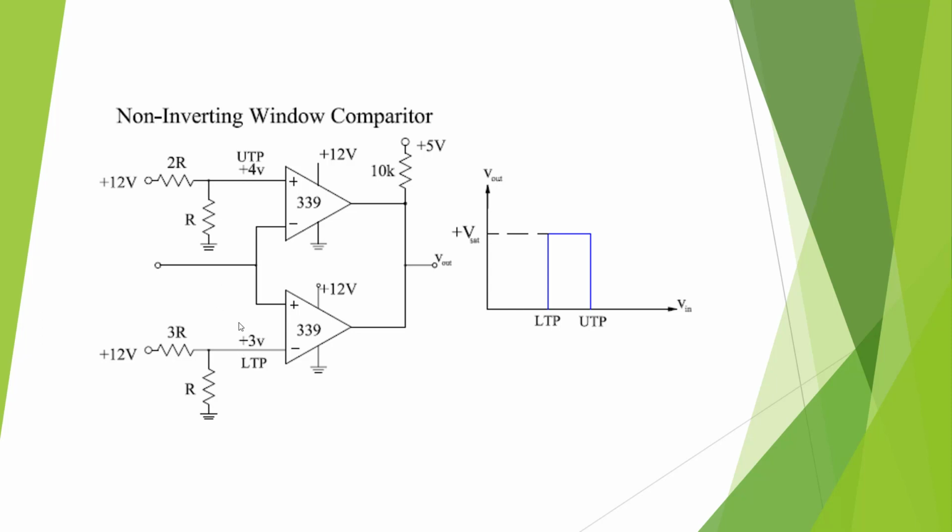Because of the way this one works, we're going to try in the middle again. So we've got 3 and 4, so let's put 3.5 in. So with 3.5, 4 is greater. So this one's going to open up and we're going to use our pull-up resistor.